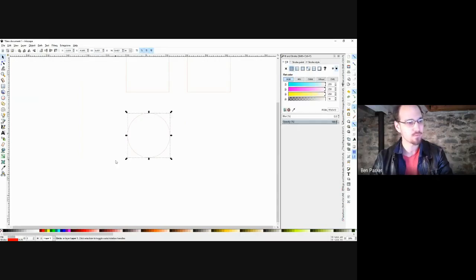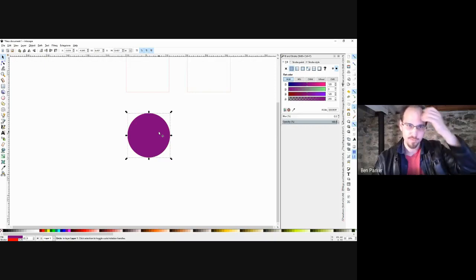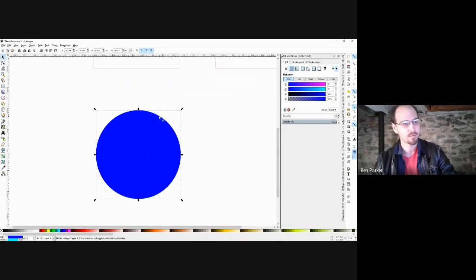Actually, I think this would be a good time to talk about color. If you're using Inkscape for maybe not necessarily the laser, maybe you're doing a card design or something like that, you're going to have different colors. We can click any of these buttons down here and give it a fill. A little bit of troubleshooting: sometimes it comes up semi-transparent. I'll go over the hiccups that can come up in Inkscape, but give it a fill of some kind, and we can hold the Shift key down and click a different one to give it a border.